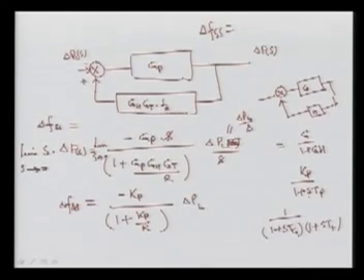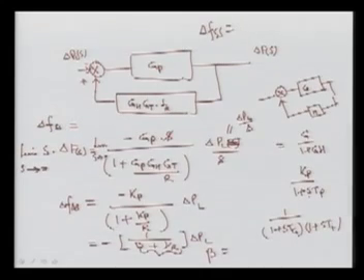So here, for that change in the frequency, we can simplify this again. I am going to divide by KP from both sides, so I can take the minus sign outside. Here 1 upon KP is nothing but your D, and here it is 1 over R, and then we get the change in the load. The component we are getting here is called B, and we will see this B is nothing but your D plus 1 over R.